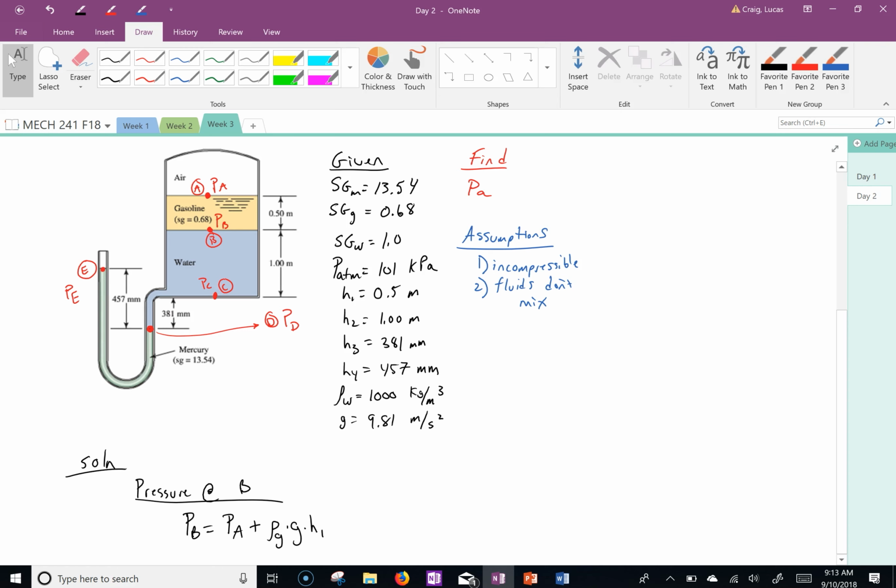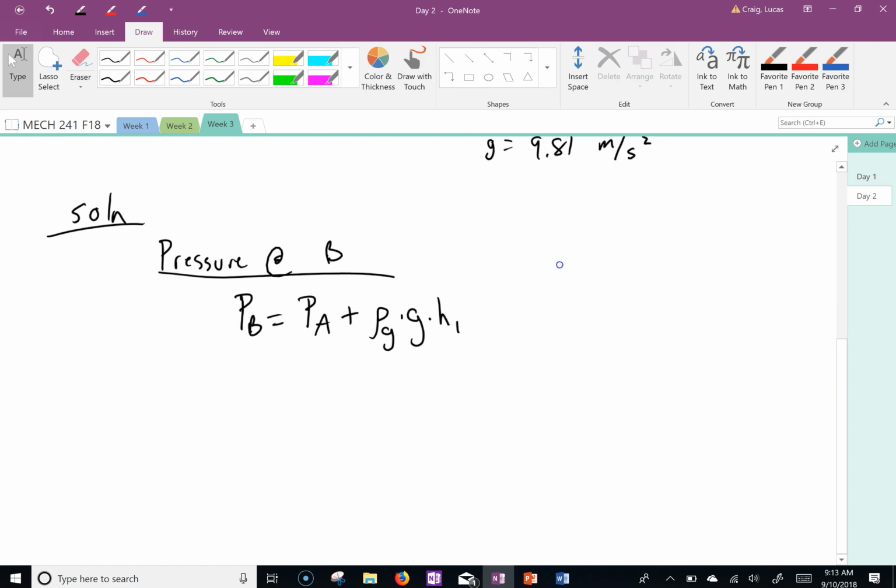And always write it so it's the bottom pressure equals what? Top plus rho GH. Always drive that in your head. Don't worry about negatives at all yet till you rearrange, okay? Trying to drill that in your head. Always remember, bottom equals top plus rho GH. So yes, what we're going to do now is we're going to rearrange for PA.